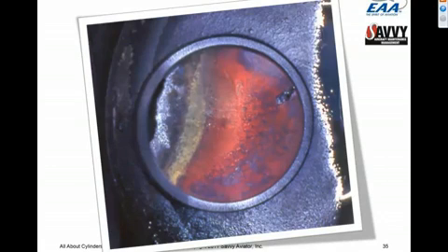You can see the color pattern on that valve face, and you can almost visualize what that valve would have looked like under a borescope right before it failed. Had we been able to visualize this valve 100 hours, 50 hours earlier, we would have definitely seen this developing. But back then, we didn't have borescopes, and we weren't able to do that kind of stuff. And so failures like this happen. But today, if you're paying attention, there's no excuse for this sort of thing happening.